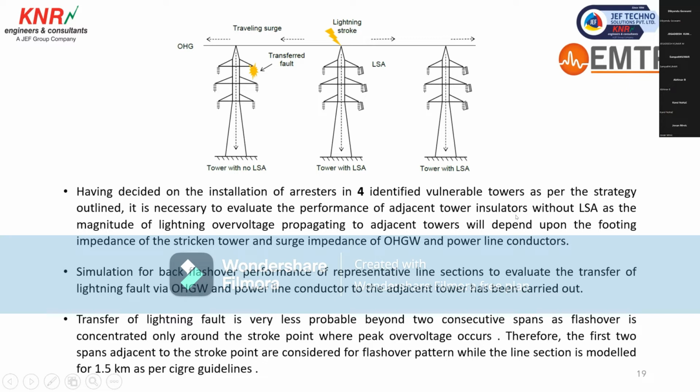The performance of the adjacent tower without LSA depends on the magnitude of overvoltage developed, which in turn depends on the footing impedance of the stricken tower.